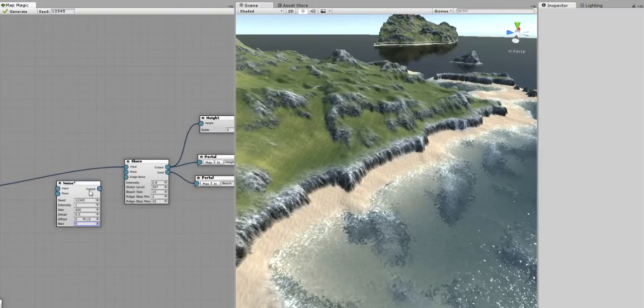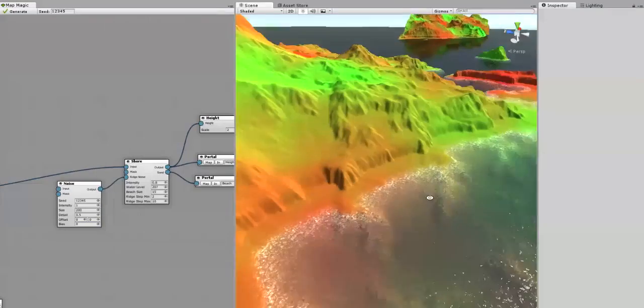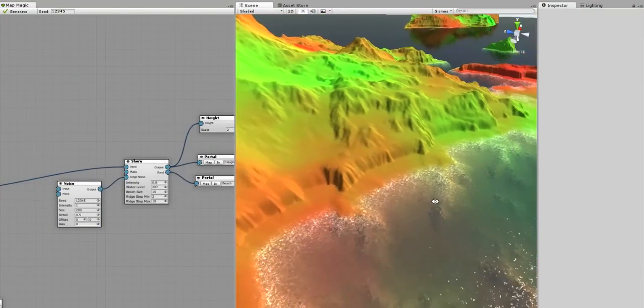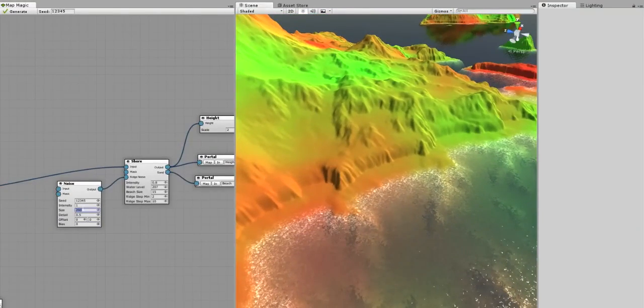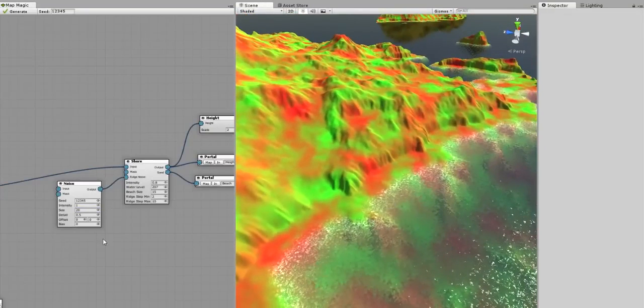So we'll create a noise map and connect it as a ridge noise input. You can see that the ridge incline became mostly average, it's about 5. Let's make a noise preview to look at why it happened. You can see that the noise size is too big, it fills everything with the medial values. So I will make the noise smaller. And then I will increase its contrast. First of all, I will raise its intensity.